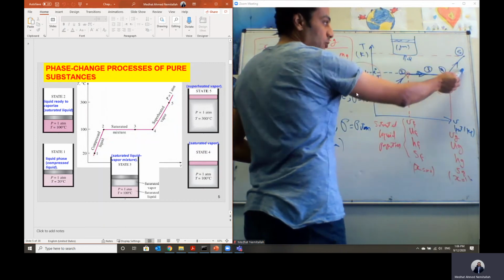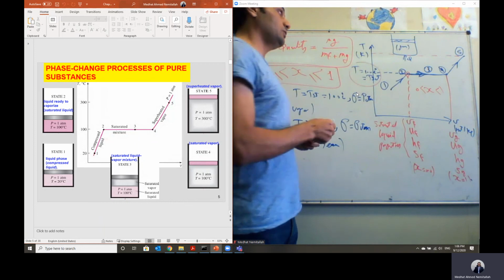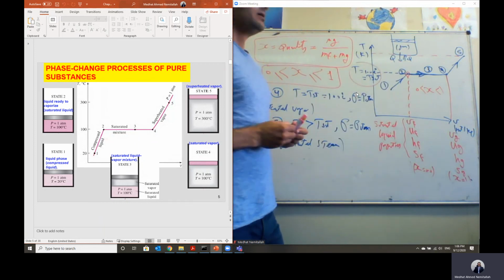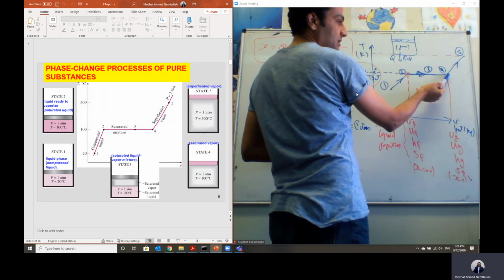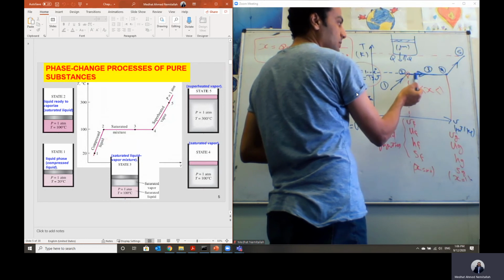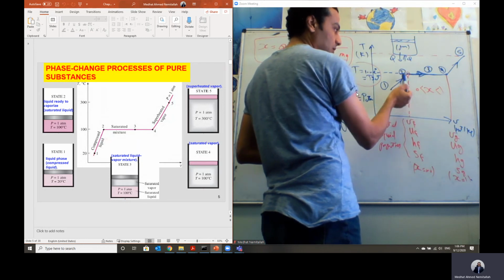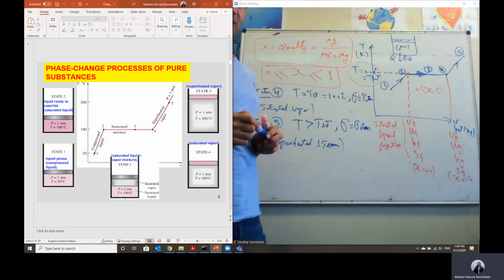If we reverse, cooling down at a constant pressure instead of heating up, in this case, we will do the same. The gas is superheated vapor. When we cool it down, it will first reach saturated vapor. Then if you continue cooling, we will have a mixture. Continue cooling, then you have the saturated liquid state. If you continue cooling, then the substance will be converted back to liquid.